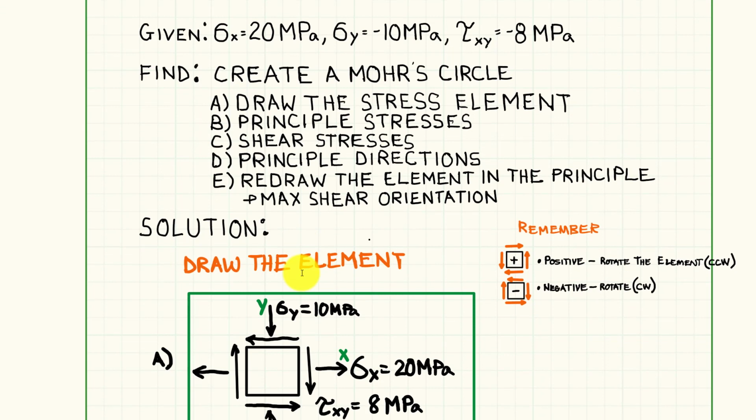Now this is an example of a Mohr circle. Yes, you need to hand in a handwritten Mohr's circle on engineering paper. You're going to use a ruler and protractor and make it look nice. Let's say that I had gone out and I calculated my stresses in the X, the Y, and my shear stress on a stress element due to torsion or some kind of loading. Okay, we need to draw a Mohr's circle.